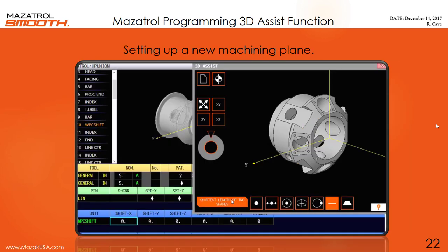This is a much more powerful example of what you can do with 3D Assist. In this case, I want to move the machine up and machine this flat, drill this hole, and drill and tap this pattern of holes. Typically in a Mazatrol program, I would shift my 0 up to the center of that hole and rotate my plane flat on that flat surface there.